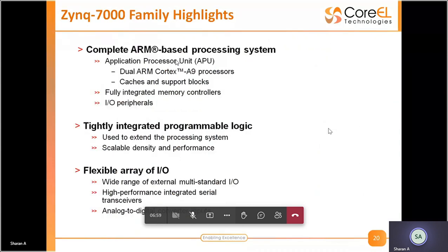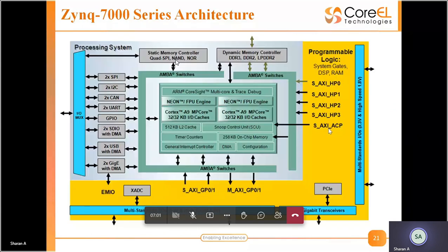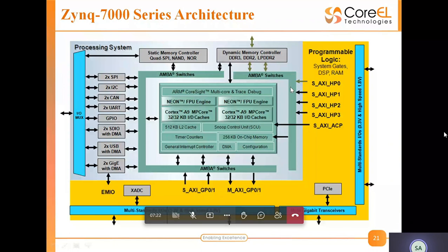so this is the entire structure of the architecture. Okay, we'll briefly explain this. So the main core area, this is the main processor here. Okay, it has various processing engines. It has an ARM Cortex A9 processor for our Zynq 7 series chip. Okay, it is surrounded by this AMBA protocol. Through that, the AXI protocol will be communicating.